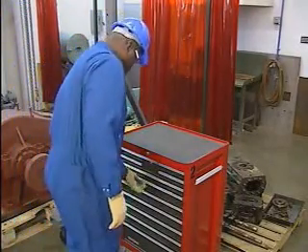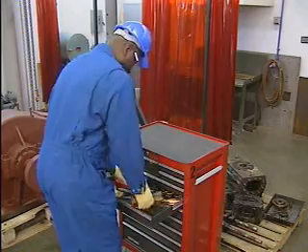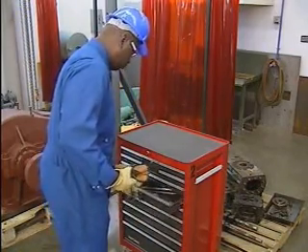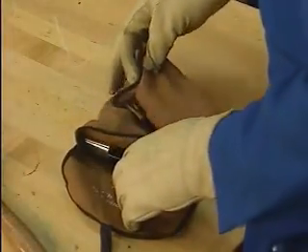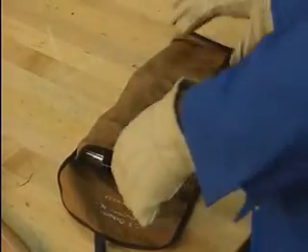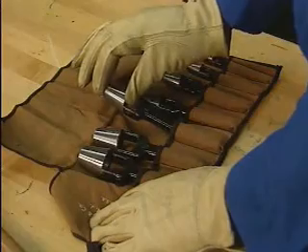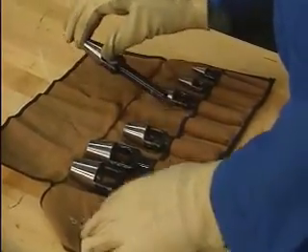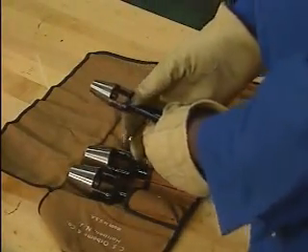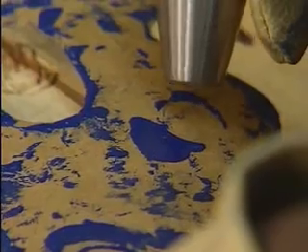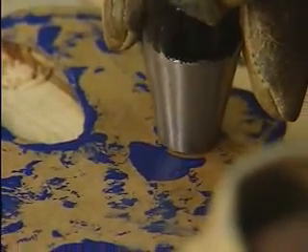When he's finished cutting the gasket to the desired shape, the mechanic uses a hole punch to make bolt holes in the gasket. A hole punch is the best tool for this step because it cuts a clean, precise hole. Well-formed bolt holes are important because they allow connecting bolts to thread easily through the gasket material to avoid tearing or buckling. The mechanic places the gasket on a piece of wood and positions the hole punch over one of the hole shapes on the pattern.